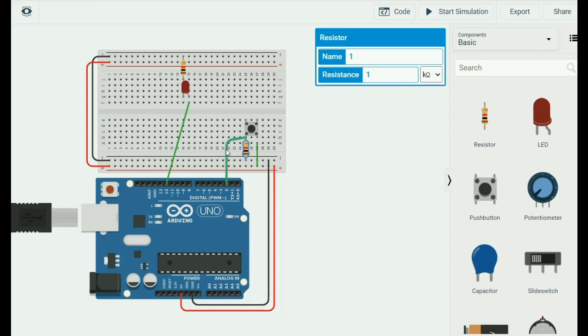It would be totally undefined. There would be no voltage to it. The voltage to it would be random if you wish. By putting this resistor over here, we make sure that this pin, through this wire and then this resistor, is seeing 0 volts.